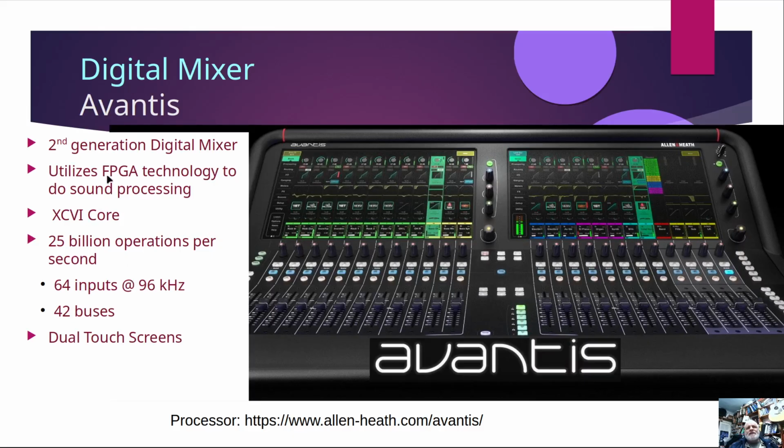But this one uses that FPGA technology. And so again, it can do something like 25 billion operations per second, converting 64 analog inputs into digital at 96 kilohertz, and then mix those for 42 outputs, and then output those 42 individual outputs.